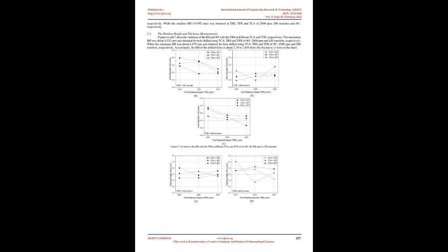In the TD process, it is considered that the sheet thickness and the hole diameter have significant influence on the bushing geometrical dimensions. Although there are other crucial process parameters, like TCA, TRS, and TFR, that exhibit a significant influence on the bushing geometrical dimensions. It is because the volume of the evacuated material from the TD material shapes the bushing. The TFR and TRS process parameters may cause the creation of cracks and petal formation, especially in TD of brittle sheet materials, like A356 aluminum alloy, due to rotating and preceding motions of the conical tool 4.